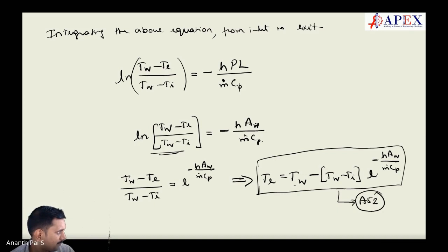So can the difference be met? Never. If it is met, it violates which law? Second law of thermodynamics. Will the mean temperature reach T wall at any point of time? Only when it's infinite does it reach. Otherwise, it never reaches. There's always a difference between wall and fluid. Okay, next.